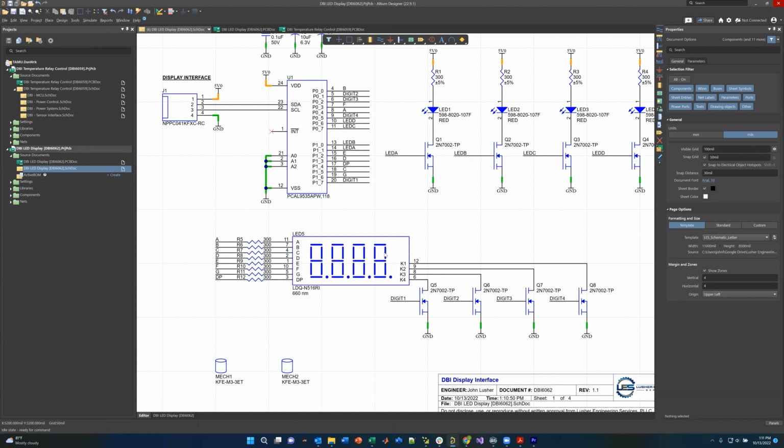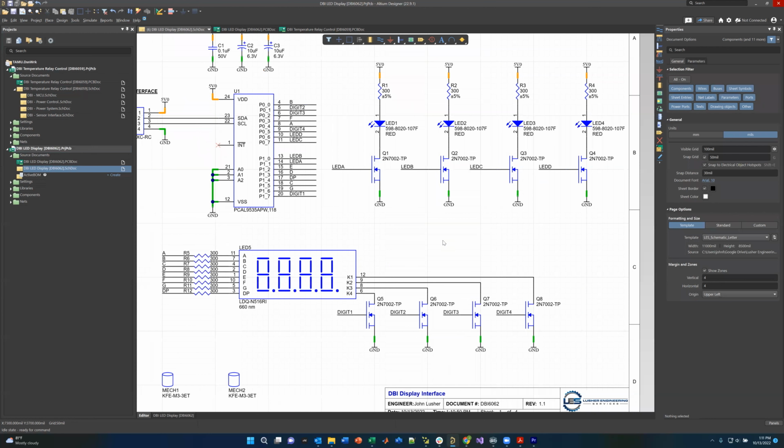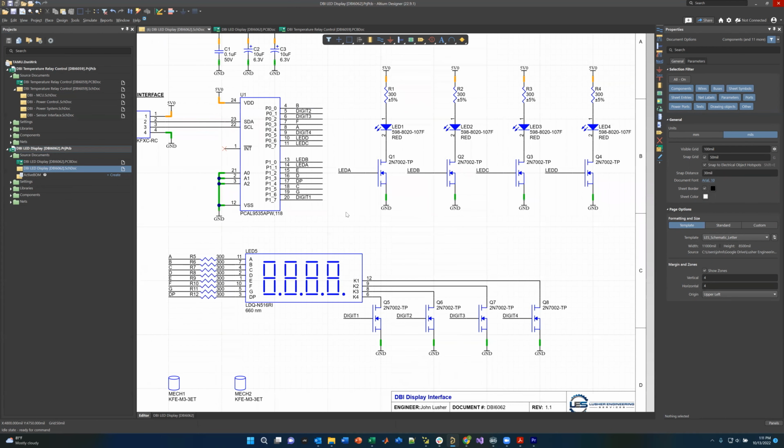So obviously, you've got to write an algorithm in code to do this, to basically turn an ASCII character into a 7-segment display character and turn on the LEDs. To do this, I used what's called a port expander, because this requires 16 I/O lines, plus these 4 LEDs for enunciators on the side of the board, which I'll show in a second. I needed 16 I/O lines.